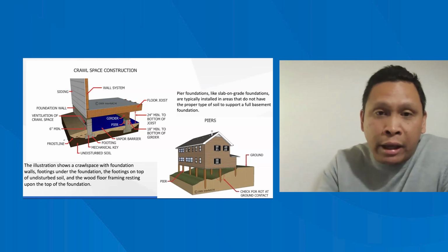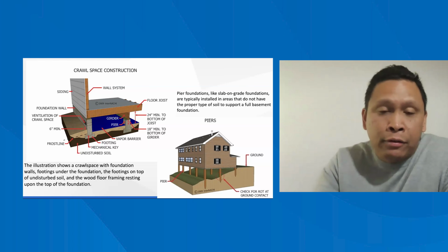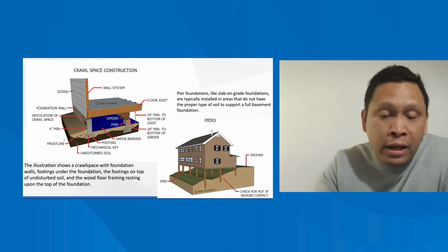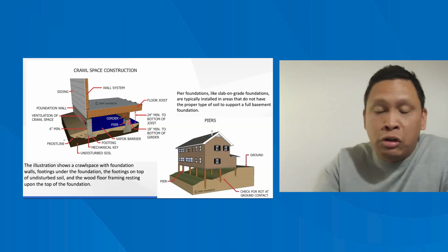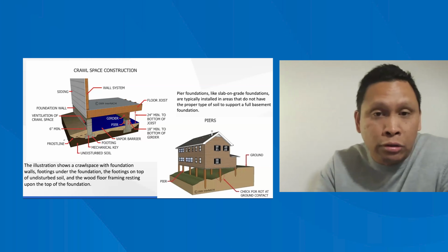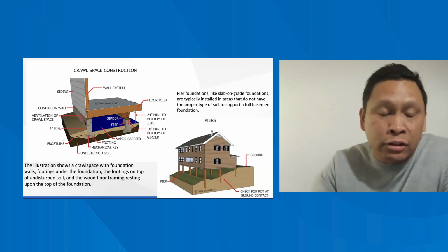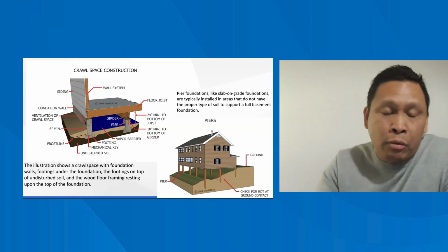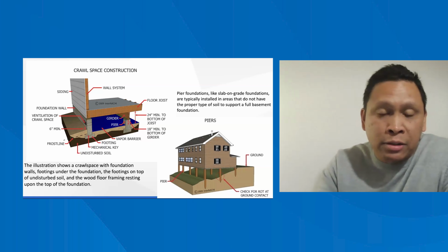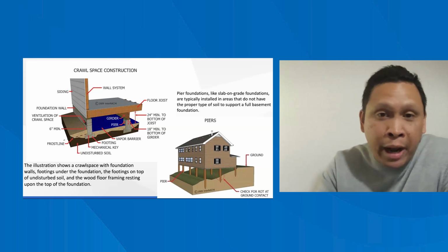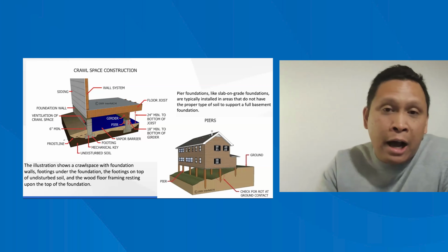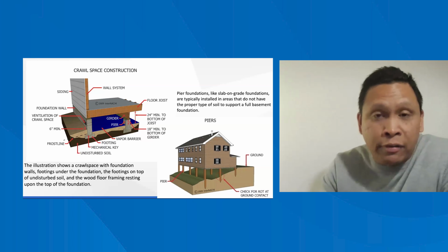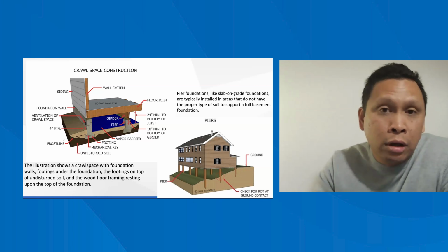You could encounter everything from supports such as the foundation wall itself to posts leaning, moving, or missing, possibly due to a gutter daylighting or discharging too close to the home, right? Grading not falling 6 inches for the first 10 feet. So we want to make sure that the soil is as solid as possible. You can see some really interesting repairs. You could see damaged floor joists. You can see rotting floor joists because maybe there isn't a moisture barrier or vapor barrier on the ground.